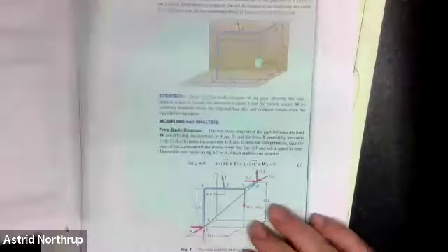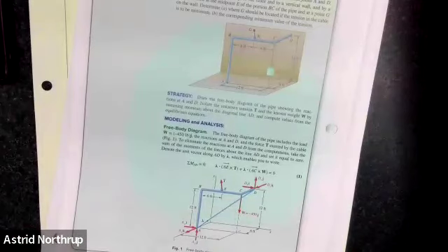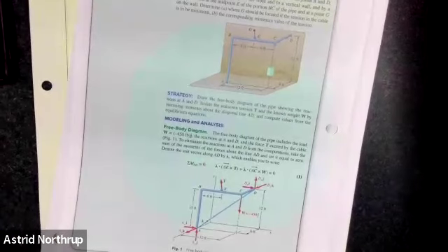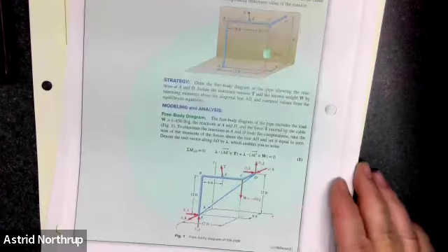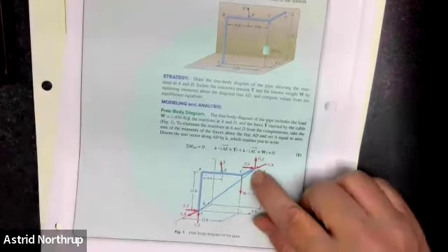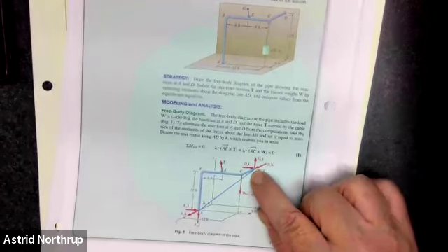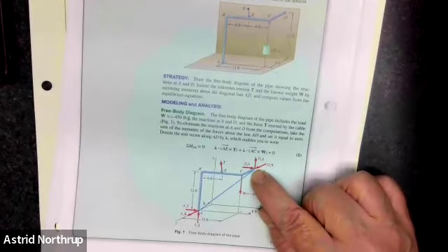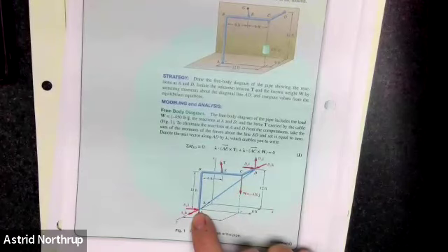And then my advice to you, if you are working a problem like this, is to go ahead and do the long work of setting up all the forces in X, all the forces in Y, all the forces in Z, and choose a point to take the moment about that has a lot of stuff you don't know. So you might choose point D, because then you're not going to have moments from any of the reactive forces at D, or choose A. It's totally up to you, but I would choose one or the other of those.